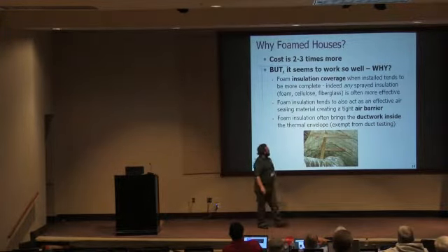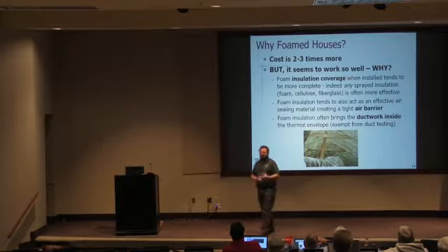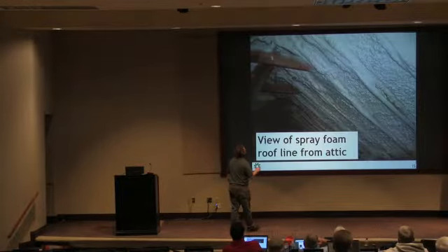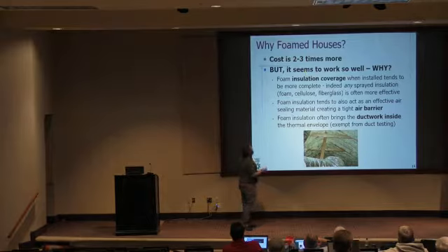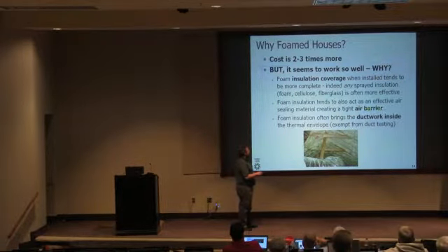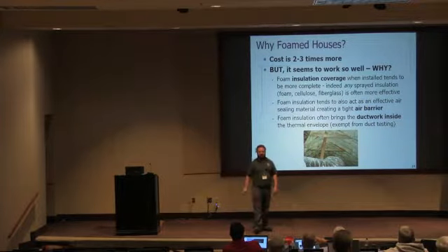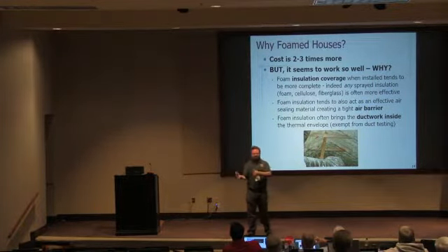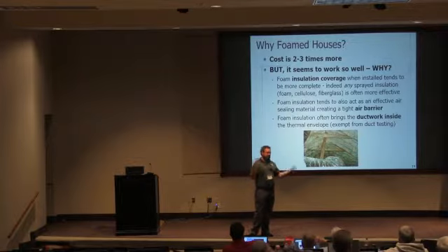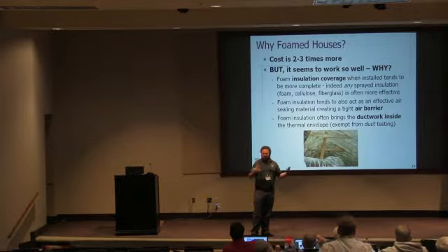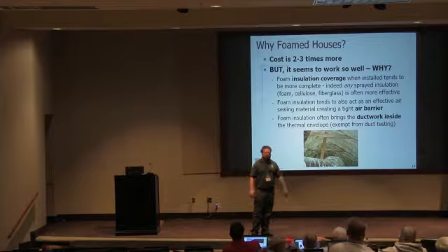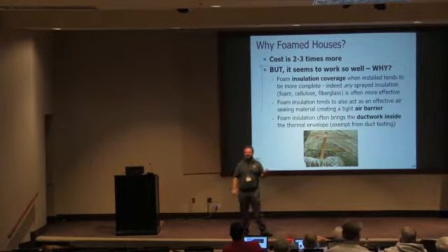All right, so why would someone spray foam a house? It costs 2 to 3 times more, but it seems like it works pretty well. And people often ask us why. And the real answer is that you get complete coverage, and that this insulation product is also an air barrier. So when I'm insulating and air sealing a home, and I'm doing a traditional batt product insulation job, or maybe a blown product like a cellulose that's not an air barrier, I've got one